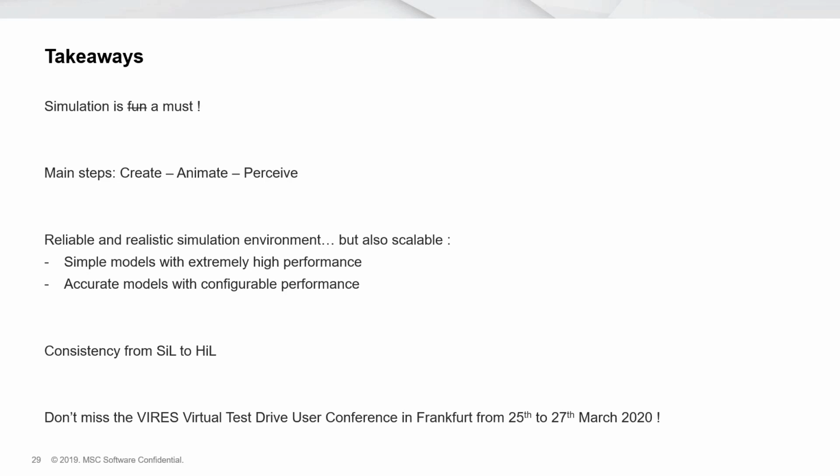It doesn't affect the system because there is no feedback, because you have open loop, or you just save the images for machine learning and train later on. You're just creating data sets. So depending on your use case, you always need to find the best measurement. But these two examples are, I think, the two extremes you have: hardware in the loop, and open loop and software in the loop systems.